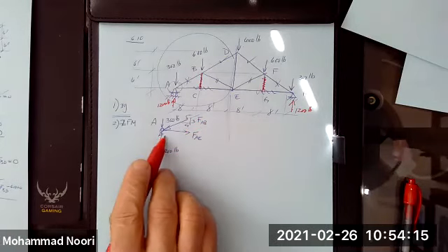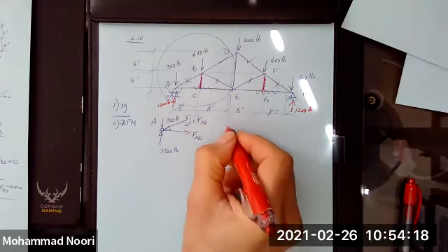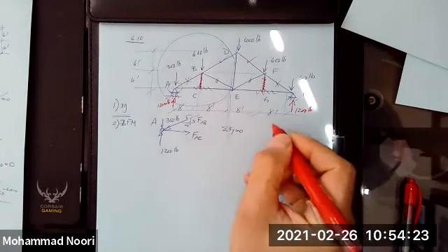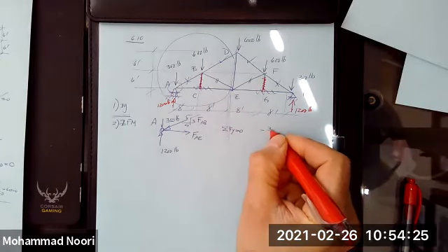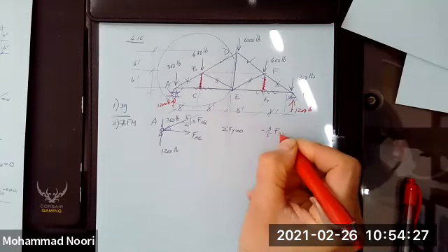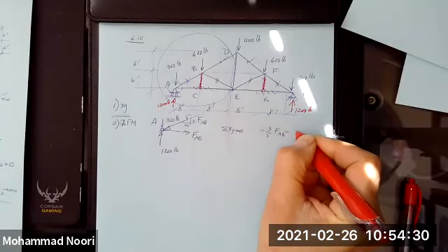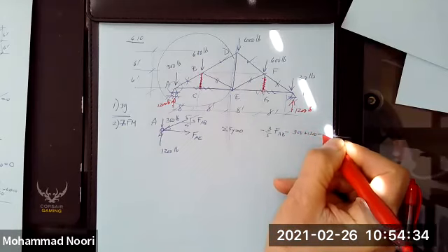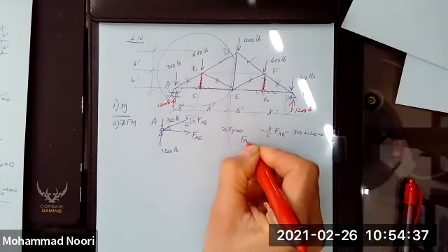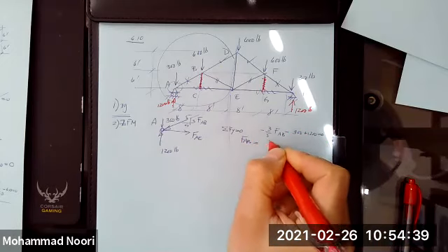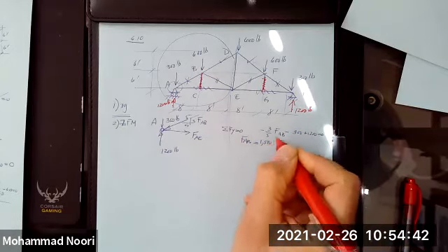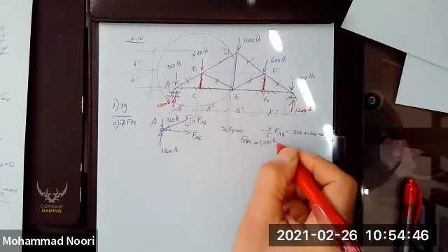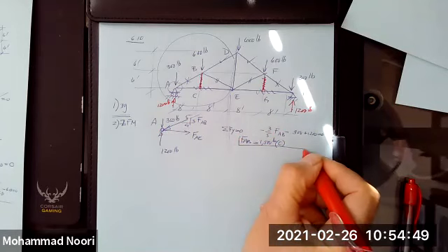Okay, so let's use that free body diagram. If you just simply write the summation of forces along y is equal to 0, you have negative 3/5 of FAB minus 300 plus 1200 equal to 0. And you find F of AB comes out to be 1,500 pounds. Force coming toward the joint, so this is a compressive force.